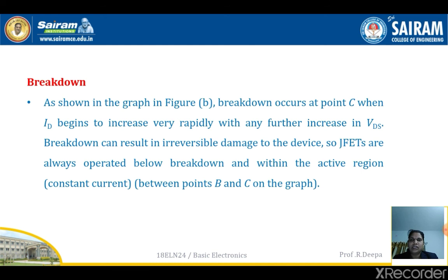And as I told, there is a breakdown region which is marked as point C in the characteristics, above which if I increase the VDS voltage, the drain current increases very rapidly. So further increase may cause damage to the device.